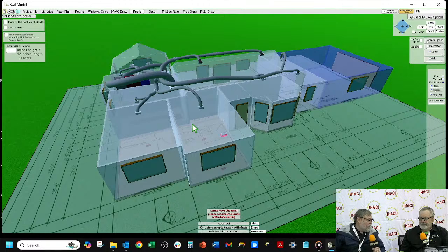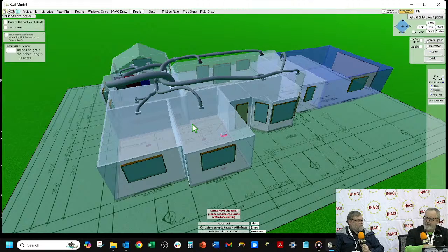We have a few more minutes because the next person's not supposed to be here until 1:30. One of the new features that we're going to add is, one of the calls we get the most is people do their design, and they're just like, I'm not comfortable with it. How do I know it's right? So what we're going to do is a self check. They hit a button and it goes through and looks at everything and looks for numbers that are kind of wacky, like your static pressure is way off, your friction rate's way off, or are you sure you meant to? Your house doesn't have any glass in it. That seems kind of weird. And it lists all the important inputs that are needed for a load calculation, and then it'll check each one.